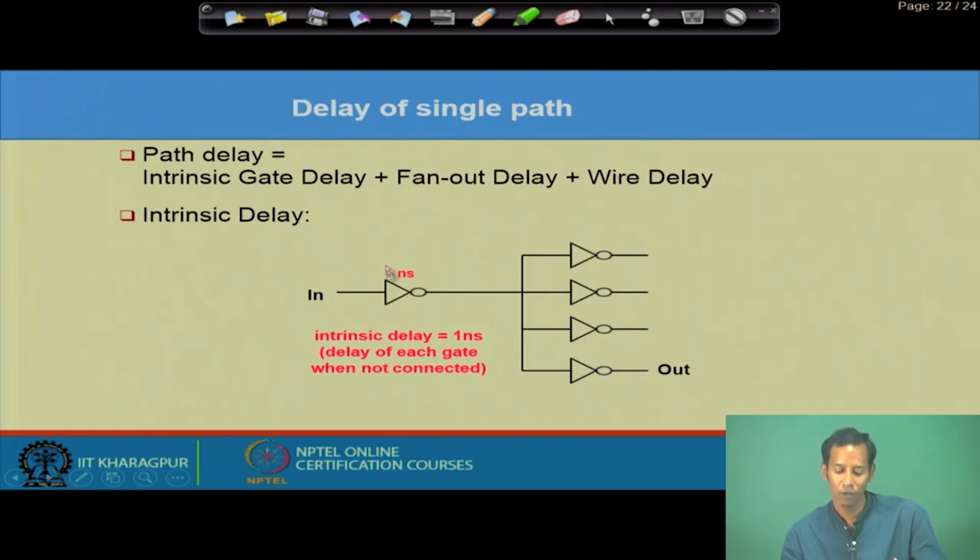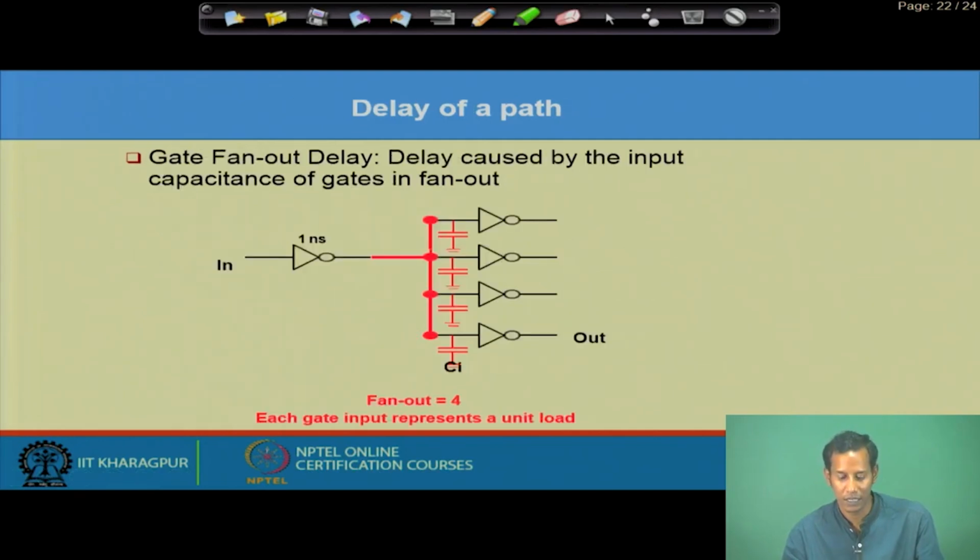then the delay will be more for this particular cell. As well, if it is driving 4 paths, that means 4 wires are connected from this particular gate, so the wire delay will also be considered in the corresponding path delay or the combinatorial circuit delay, as this fan out is 4.